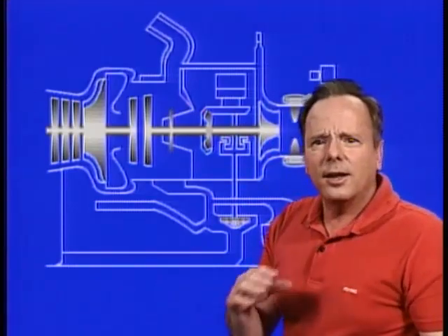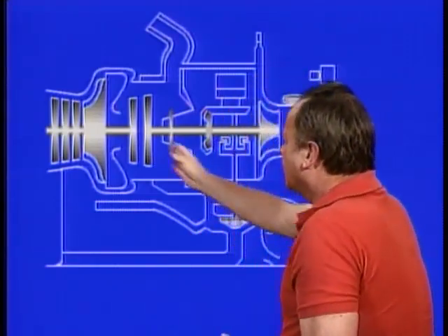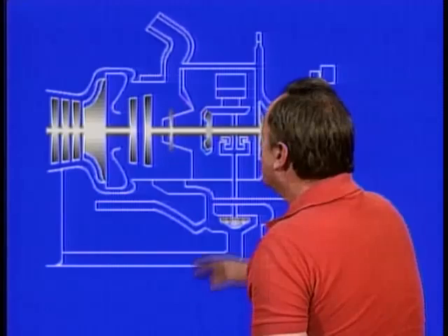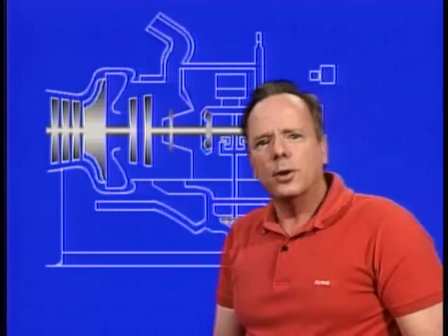So how do you regulate this? Well, you can do it several ways. You can regulate the fuel to it, but you can also regulate the pneumatic loading on the APU. Now, you might say, how do you regulate the pneumatic loading on the APU?